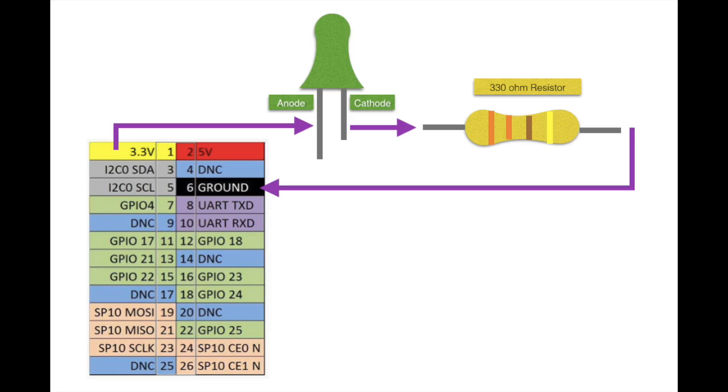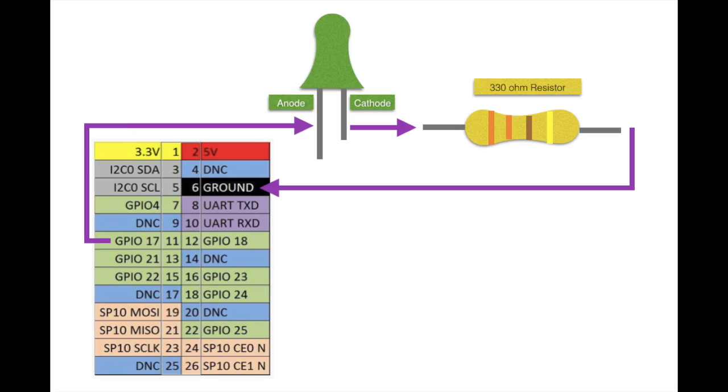So what you can see is that we currently have our LED connected through the 3.3 volts on pin 1. What we're going to do now is change that to be connected to GPIO pin 11. Please be careful here because you'll notice that the description next to the name is GPIO 17, but I'm going to keep referring to them as the pin number, which is the inside number there, pin 11.